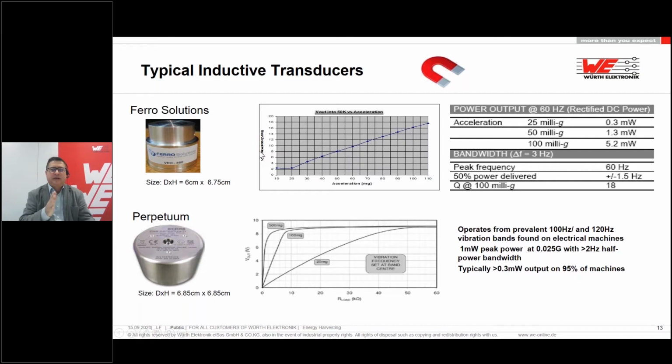They harvest the vibration on the train wheels, and they are also in a mesh network, and give information to the gateway. In case one of the wheels gets a crack, the fingerprint of the vibration changes, and then the gateway can communicate via mobile network or satellite network and give information to the train management that you have to take care of one wheel on wagon 5, which has a crack, and you should slow down or stop the train, whatever, depending on the system.